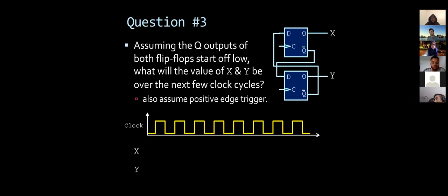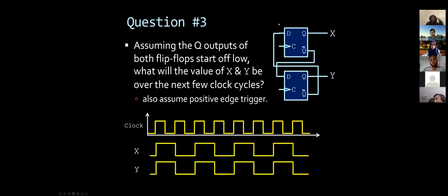Again, you can experiment at home, but I'll just show you in the interest of time how it's going to work. This is a properly built set of D latches, and they're essentially like flip-flops nicely connected with each other. They actually behave the same way, as you can see in this figure. At the beginning, when you start with zeros and the clock goes up, look here, what's the input? You start with low, so your signal is low. This goes as an input here, and this goes as an input here. So they have the same input at the beginning, because both start with low.